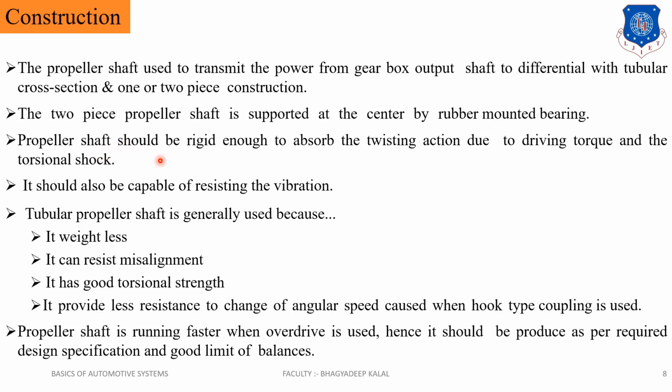The propeller shaft should be rigid enough to absorb the twisting action due to driving torque and the torsional shock. The torsional shock also comes on that shaft and can be absorbed by it, so the shaft is designed to absorb twisting stresses, or torsional shocks. It should also be capable of resisting vibrations. Due to unbalanced load or unbalance of the engine, vibrations come on the propeller shaft, so it must be designed to resist vibration.